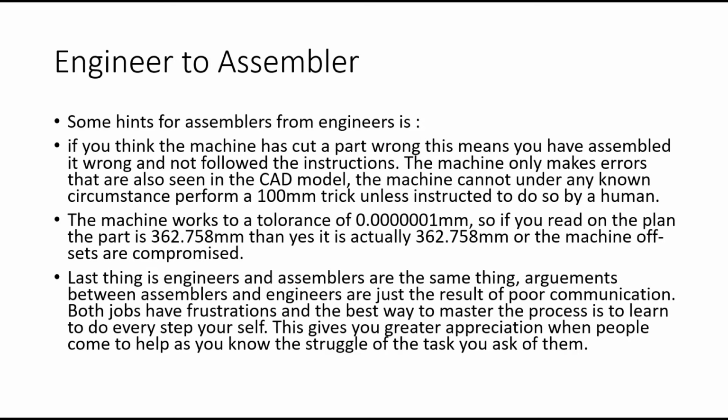Depending on the CAM program you're using, most of them are pretty intelligent this way and shouldn't stuff up, but I've seen some machines out there that do. So if you're cutting with an 8 mil bit and your part's 16 mil too small, that's a hint that you probably cut on the wrong side of the line, so its C value in the coding was probably wrong.